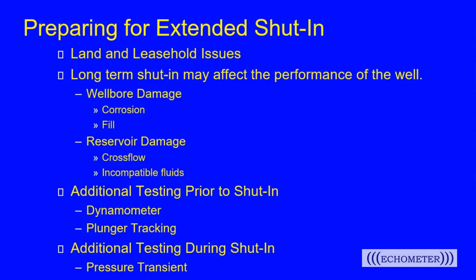The thing I'd like to do, with any shut-in, if I know ahead of time, besides shooting the liquid level, is just some other tests. We talked about pump wells last time, but I often like to get a baseline dynamometer to see what it was like before we shut it in, so we could tell if any problems occurred.